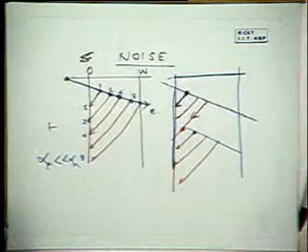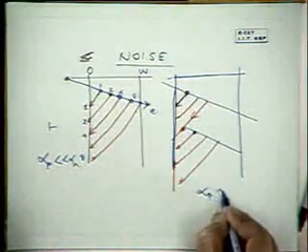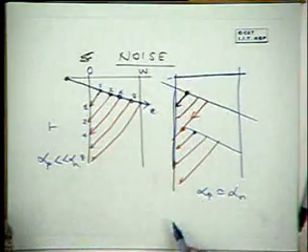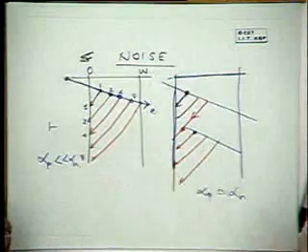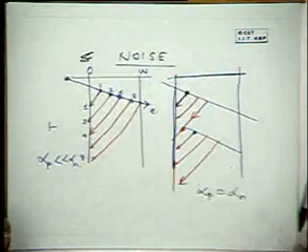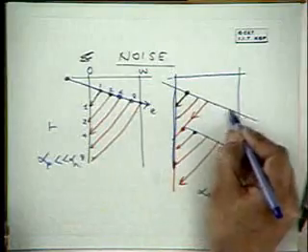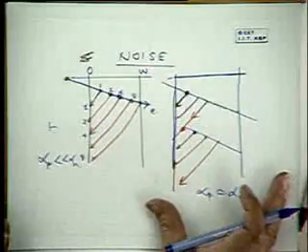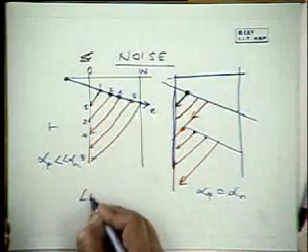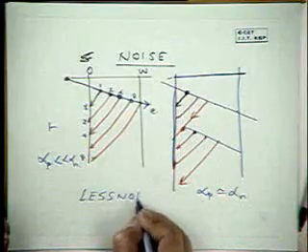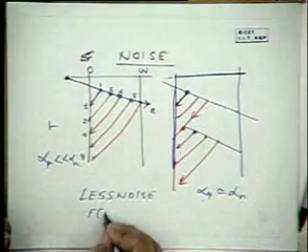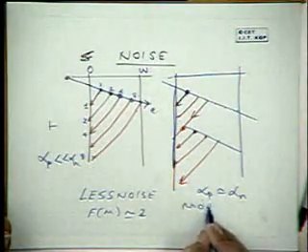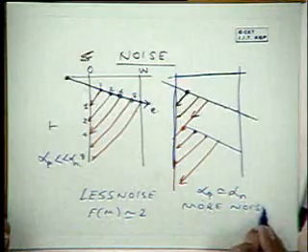So this is the case where alpha P and alpha N are both appreciable. So there is more statistical noise because there is avalanche multiplication going on in this path as well as this path, and so this is much more a random process, and therefore this is where you have less noise, FM about 2, and this is more noise, Fm proportional to m.